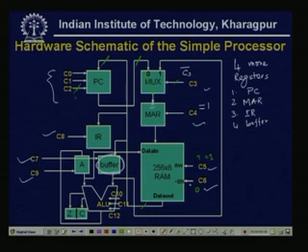So, C6 complement will be the enable line, then it will be a read enable. Then C7 is this buffer activated; C7 is 1 means buffer is activated. So, the data from the memory is stored in the buffer. This line will be activated. So, M of MAR is assigned to buffer.